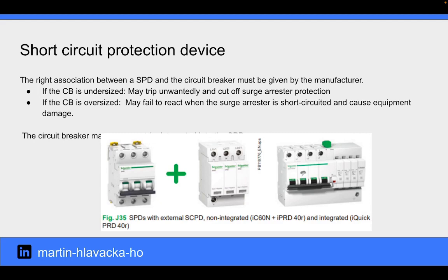The manufacturer must provide a correct association between SPD and the circuit breaker, because if the circuit breaker is undersized, it may trip unintentionally and cut off the protection of the SPD. In case the circuit breaker is oversized, it may not react when the SPD is short-circuited and can cause damage to the equipment. The circuit breaker may or may not be integrated into the SPD, making it easier to select and install.